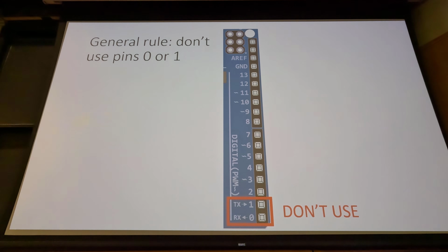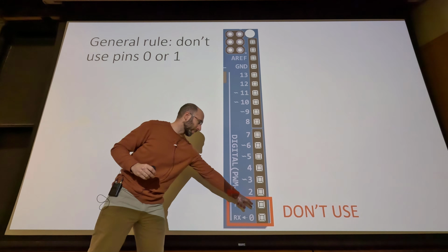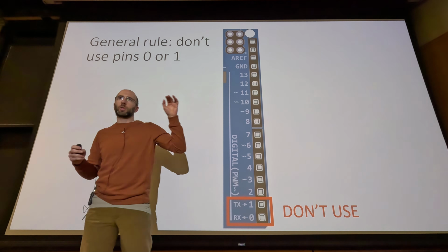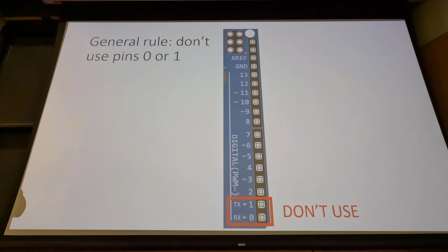If there's nothing else connected to your Arduino, you can hook your oscilloscope up to these pins and you'll see the voltages on those pins fluctuate when you upload a program, because that's how it's sending the data over USB. I don't think it actually matters in Tinkercad, but with your physical Arduino, skip using those going forward unless you've filled up all the other pins and you have to.